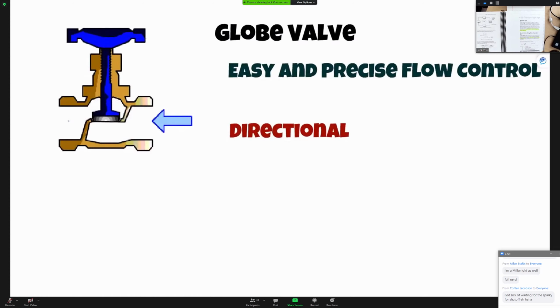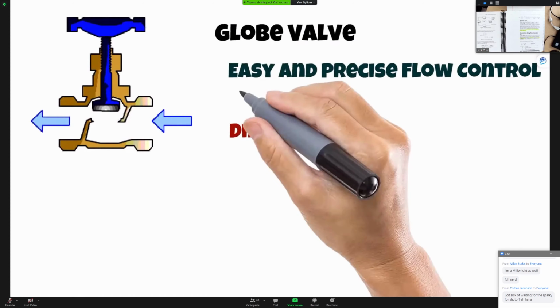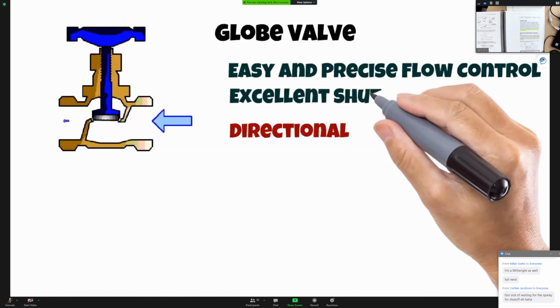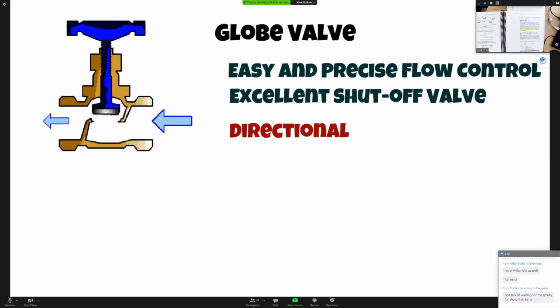They are also used as end termination shutoff valves, when installed correctly, for example, at a tap or faucet where flow control is required, as well as a perfect shutoff with an excellent seal. Globe valves should never be used as shutoff valves in between a piping system.